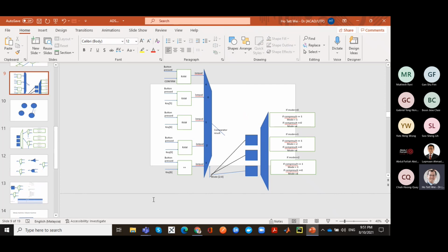And this is the idea of what you have heard in maybe processor circles as microcode. Microcode is nothing else but you are implementing the combinational logic, the processing work, as a lookup table using memory so that you have the flexibility to reprogram things. And why would you want this flexibility?